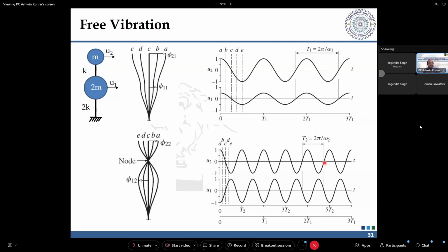And the third one is, if I subject this particular structure to a particular ground motion, the final response of this structure will be an amalgamation of all these modes, all these vibrations that are coming in here, right? You can understand, during an earthquake, whatever that accelerogram showed, it was a varying frequency, varying acceleration. It is not a sinusoidal forcing function where you have a fixed forcing frequency. It is an earthquake which can have multiple frequencies coming into the picture. So the final response of a multi-degree of freedom system will be an amalgamation of all these mode shapes that you see here, right?